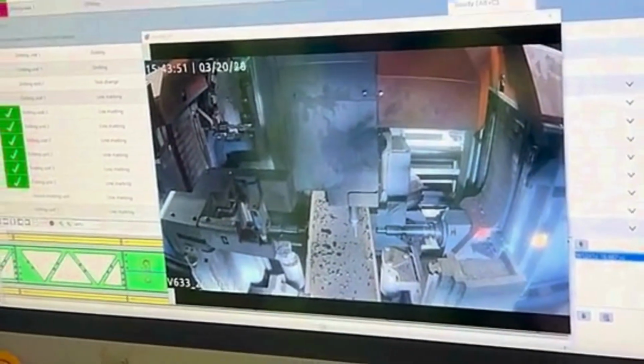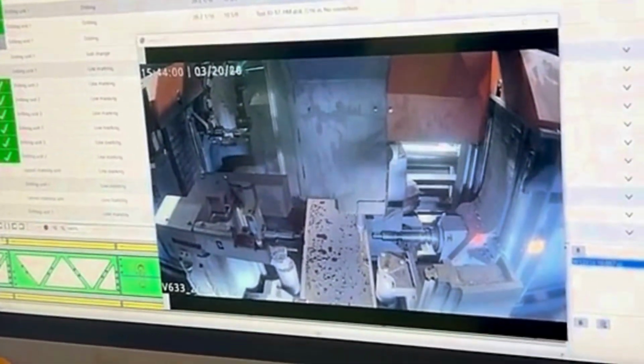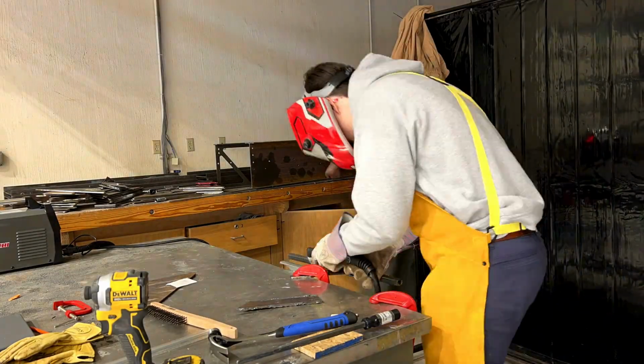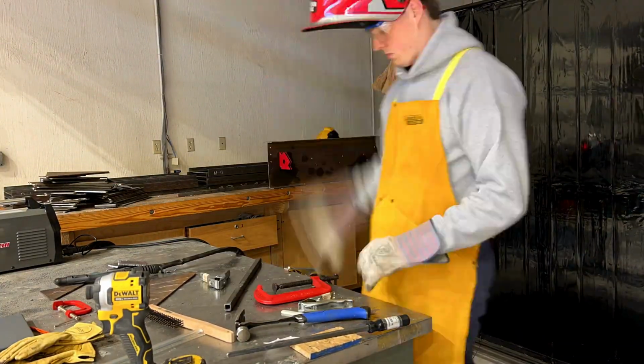Because of this, we had to develop the CNC information using Vortman's VACAM design software, which provides code to the machine for it to run. This was certainly the most challenging part of the entire process and required heavy collaboration with W&W AFCO Steel employees. Once the stringers were CNC'd, we started in-house fabricating the splice plates, horizontal braces, and footers, all from the waste material in the CNC process. Yet another way we ensured sustainability in our design.